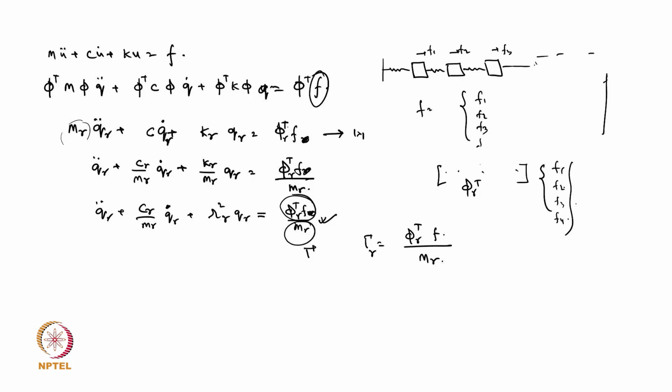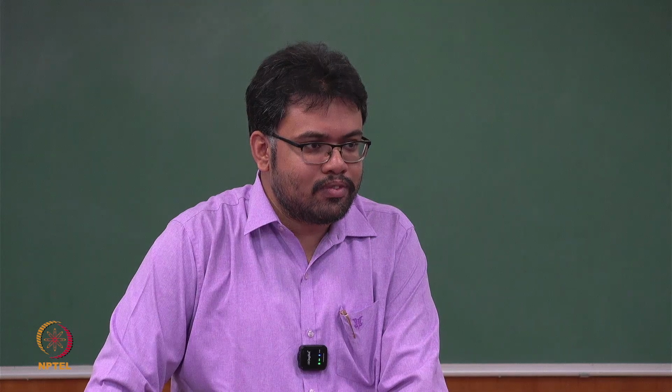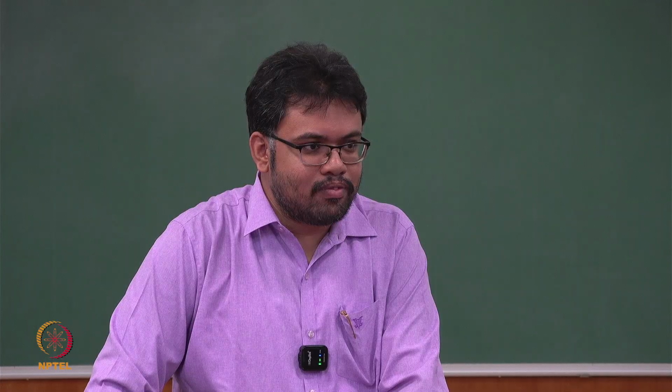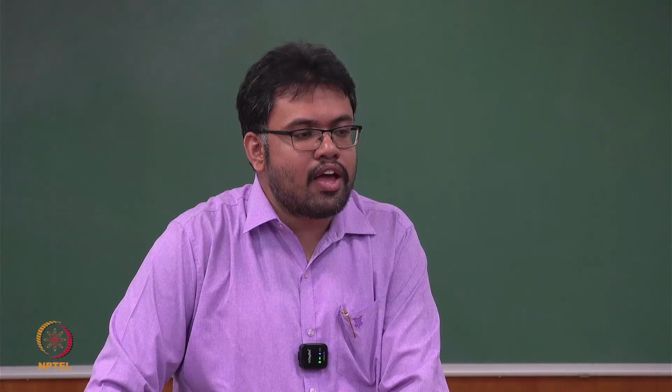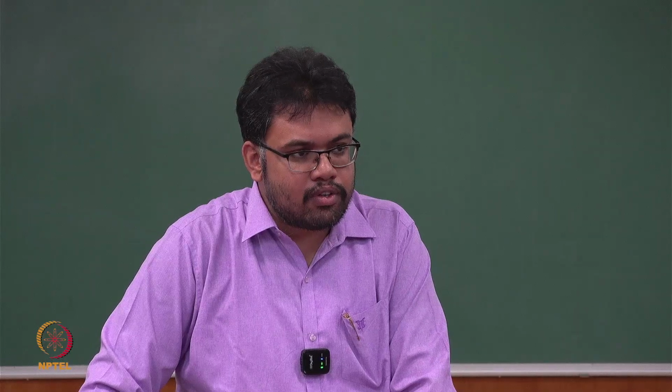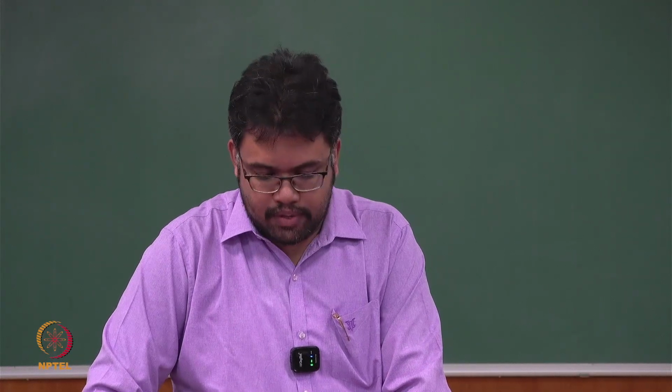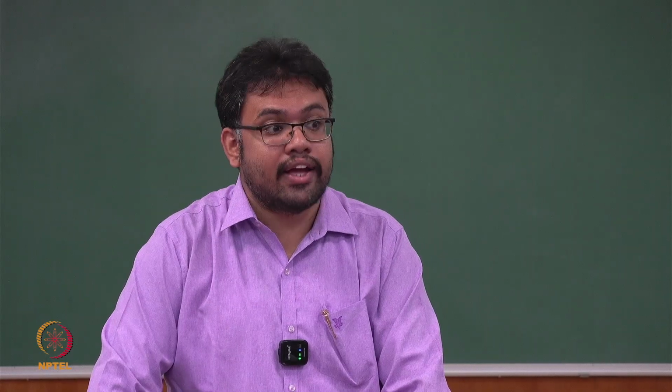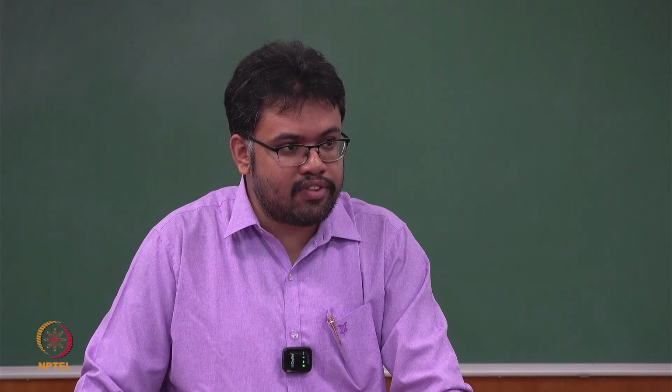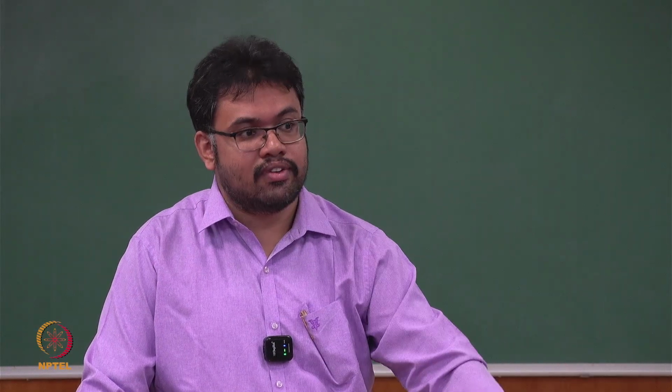Now maybe if you try to see how it is written in the code, W, it is phi transpose. That is the total mass, the modal mass ratio, which should be 100%. That is not that one, that is the modal participation factor. This is the mode participation factor, and that is the mass participation. So those two things are different.